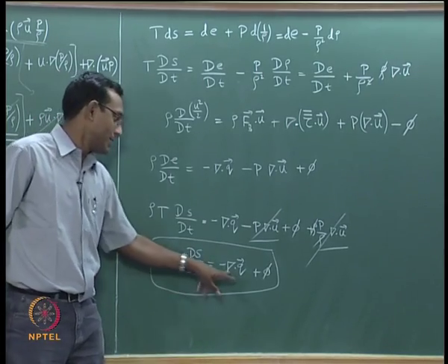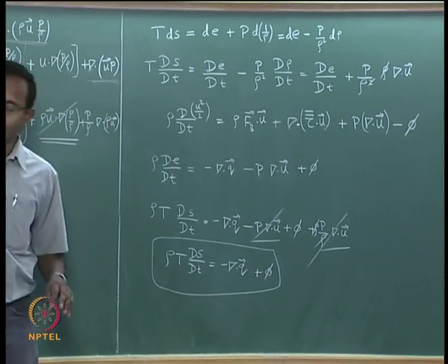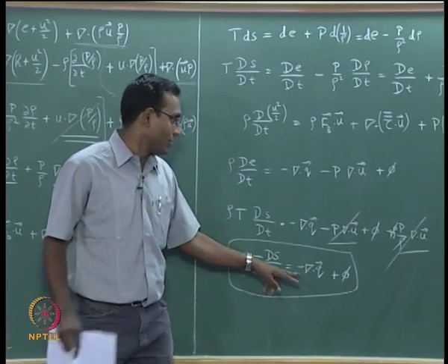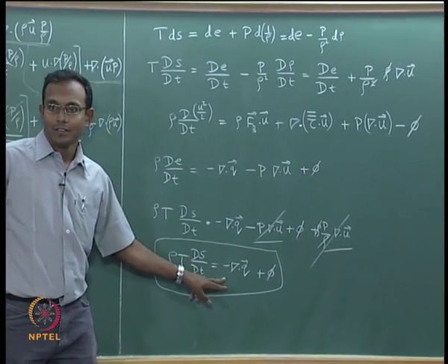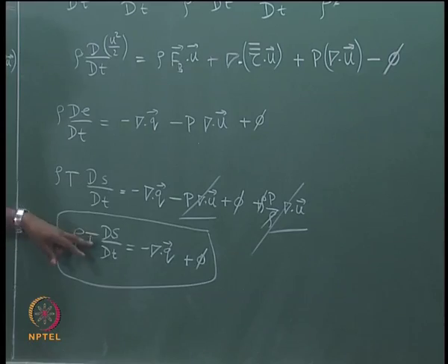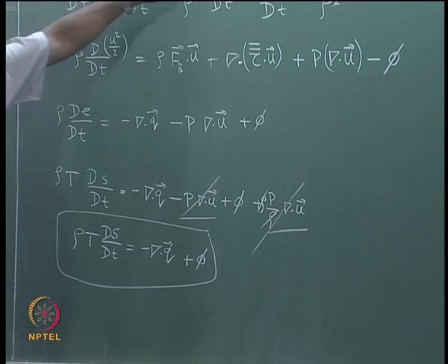Okay. These are my predominant changes in entropy. Entropy changes are mainly due to this. Of course, we also know that there is one more way we can change entropy, that is through shocks in the flow, okay, which is just sitting inside this, which we could not talk about here. Okay. That will come as delta P naught, that will not be from here, that should come from the direct expansion of this term.